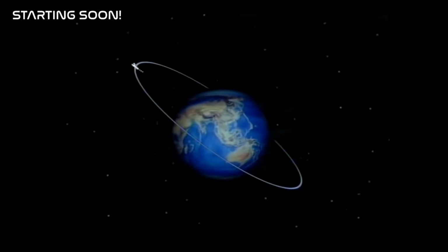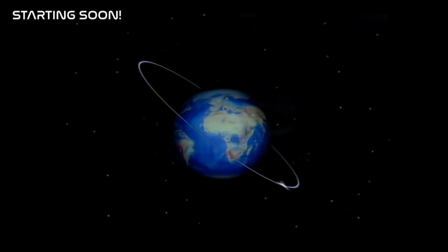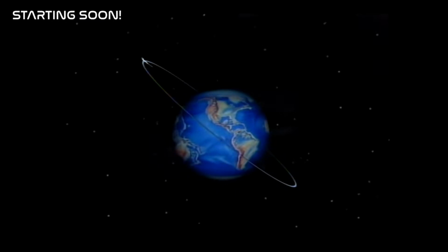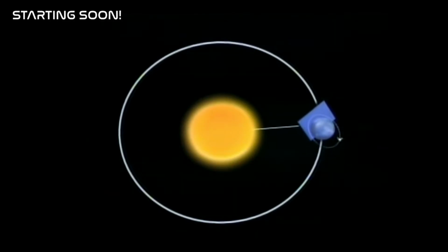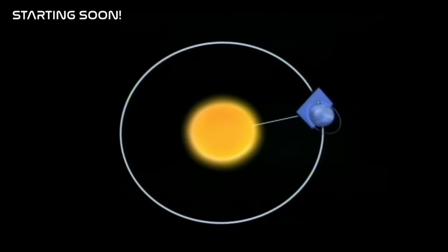Another frequently used orbit is known as a sun-synchronous orbit. These take advantage of the precession of the orbital plane caused by the Earth not being a perfect sphere. All sun-synchronous orbits are highly inclined retrograde orbits which precess eastward around the Earth's polar axis at the rate of 1 revolution per year. Since the Earth-Sun line also revolves eastward at the rate of 1 revolution per year, the orbital plane will maintain a constant orientation relative to the Earth-Sun line.